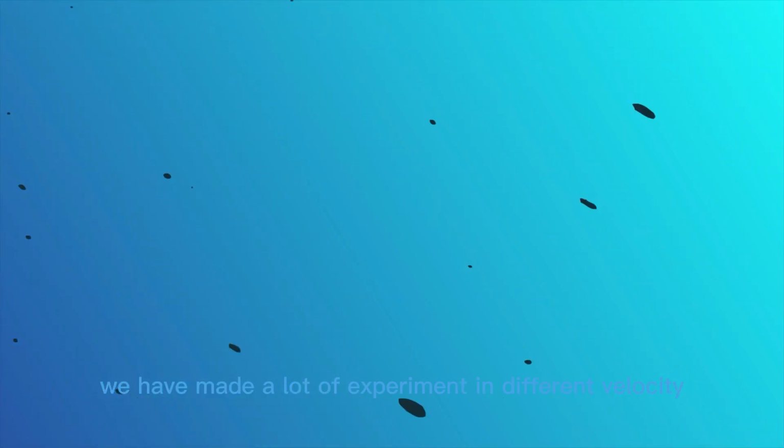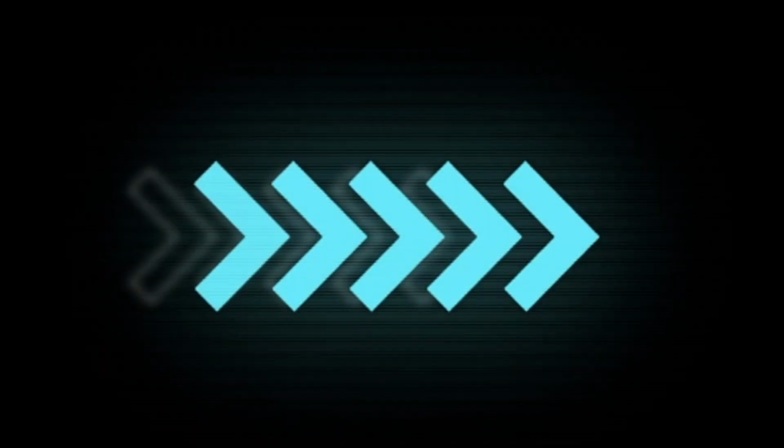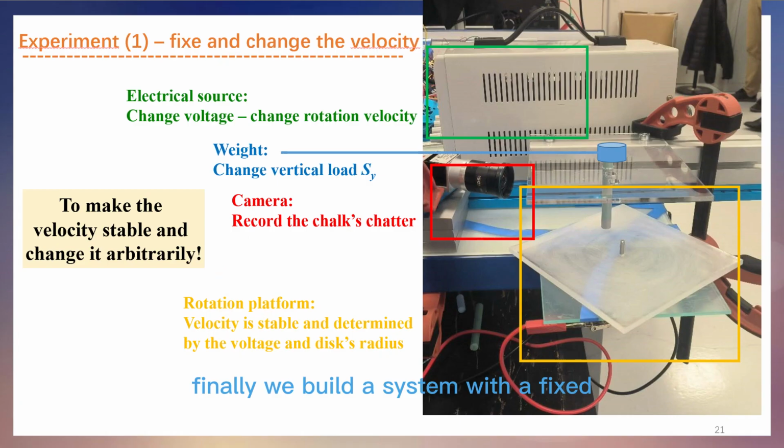We have made a lot of experiments at different velocities, and we find from the results that even at low velocity the chatter happens, but with low frequency, and the length affects the frequency more greatly than controlling the force. Finally, we built a system with a fixed radius of rotation for constant velocity.